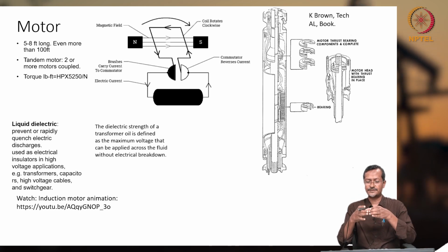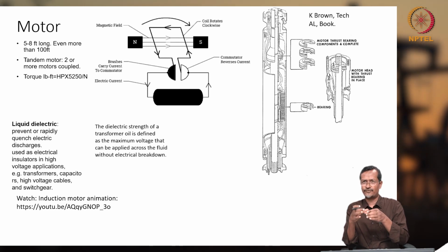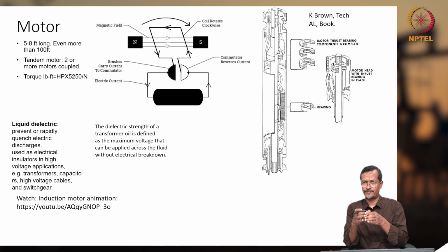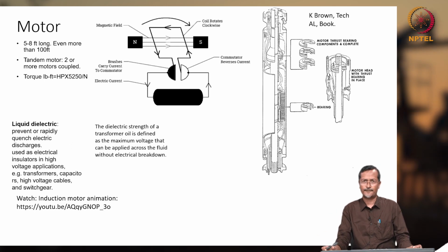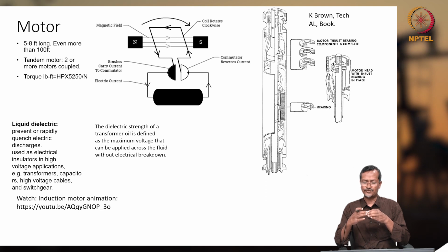you have narrow space, casing size normally 6, 7, 8 inch. So within the casing the tubing will be there, and inside the tubing the motor will fit, so it will be 4, 5 inches maximum, most probably the majority will be 4, 5 inches or 6 inches.